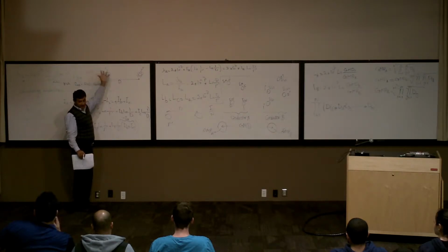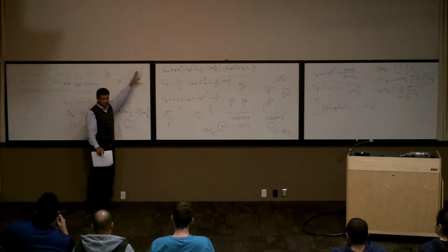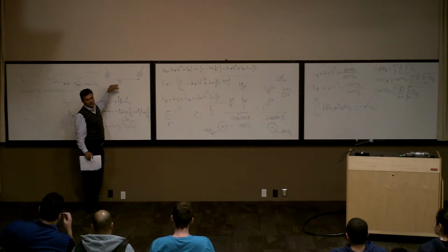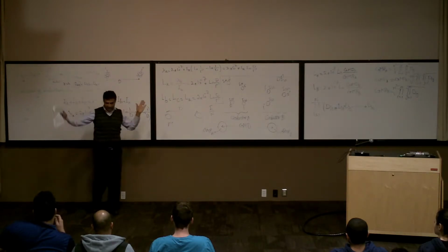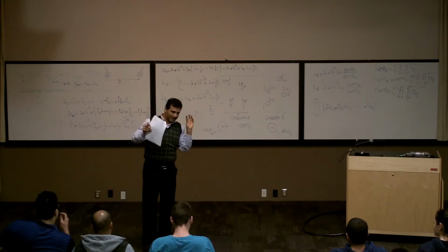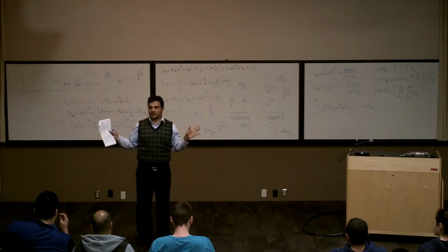But now for the GMD, I should go from this conductor to this conductor to this conductor to this. It's going to be a lot. But if this D is much bigger than the R, the GMD is going to be D. If the distance between the two conductors is much bigger than the internal distance between the strings, the GMD is going to be D.